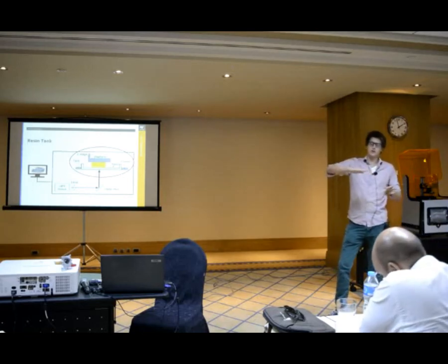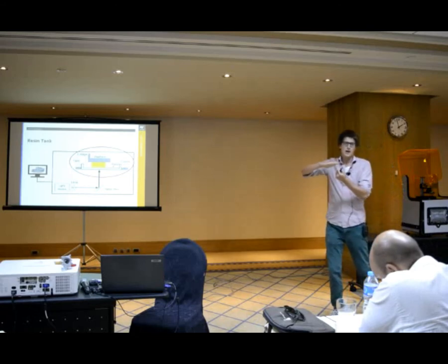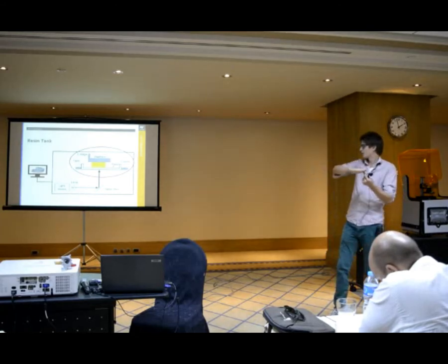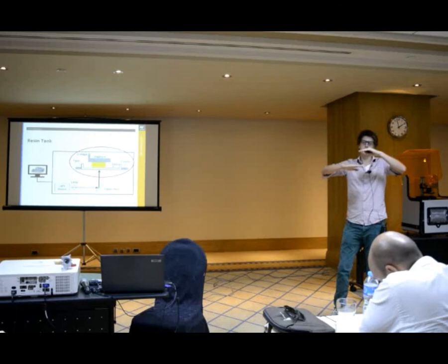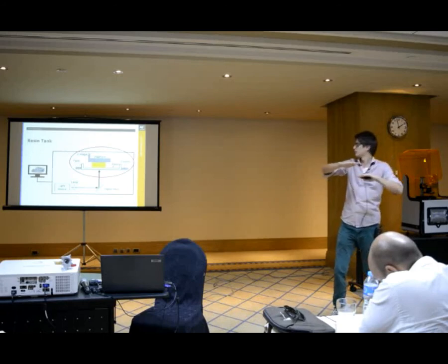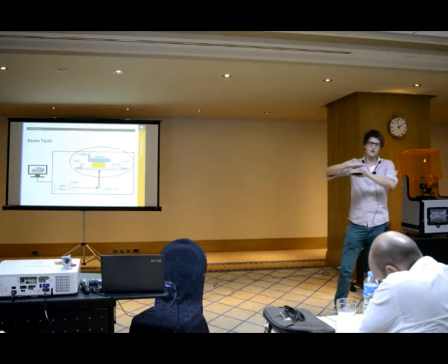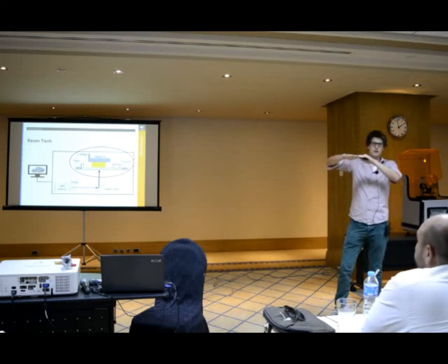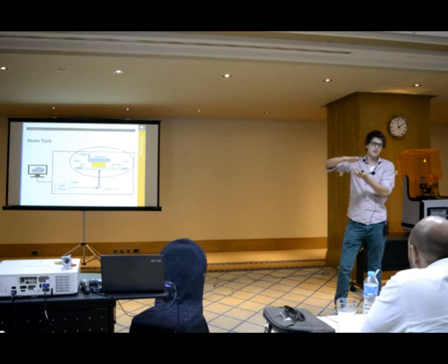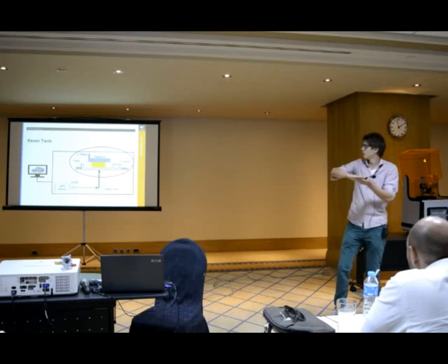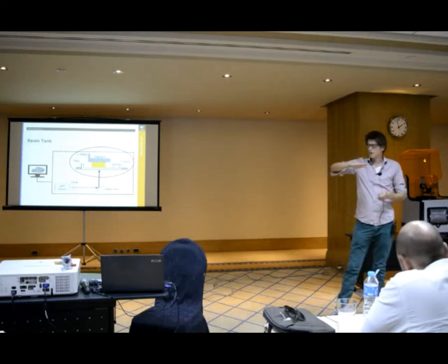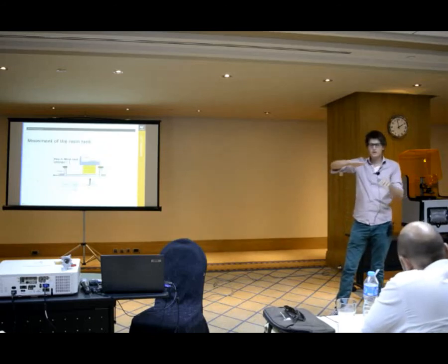If you would pull up, you would cure one layer, and then this layer is attached to the previous layer, but it will also attach to the tank itself, to the bottom of the tank. This is not desirable, of course, because if you then pull up your Z stage, you might crack your structure and it will fail.